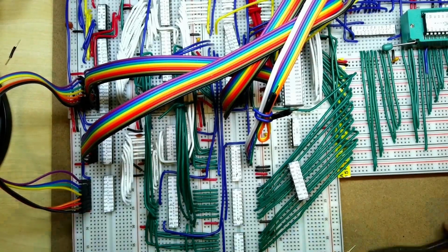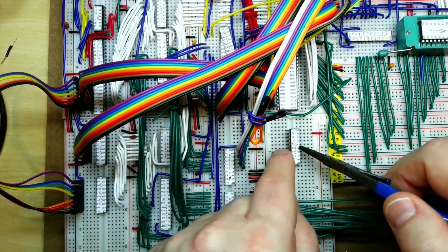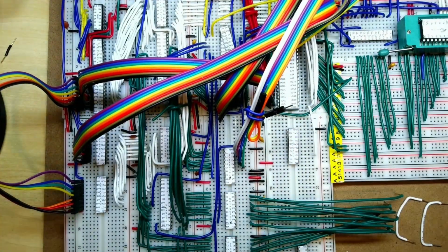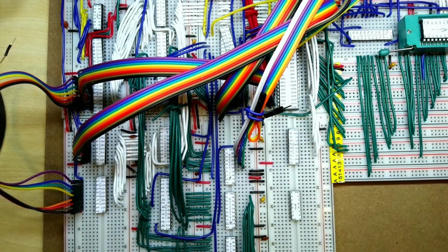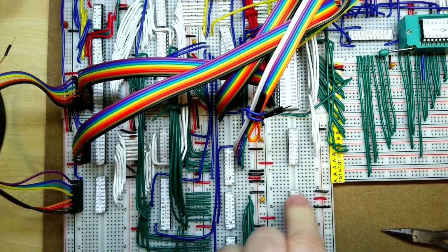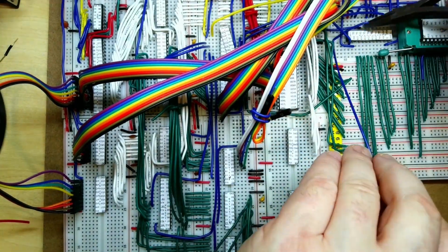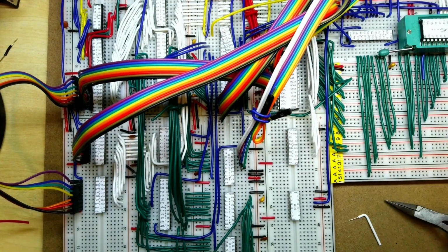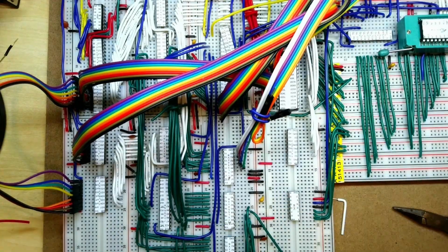So now we're going to put in the page register and also then put in the address decoder in a minute. So we're just wiring in 4 data signals there for the moment. Then we'll put in the address decoder, and this is going to be driven off the CRT3 line. So we're just wiring in the CRT3 enable line there, and then we need these 3 address lines, A7, A8, A9, to then break that address range down further into the 8 subdivisions.